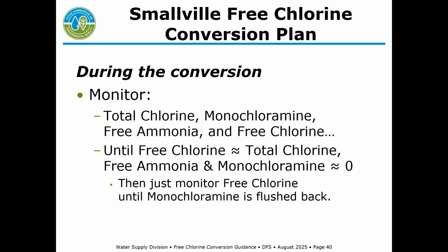And I'm just reiterating, I know I've said this before, but you're going to monitor total chlorine, monochloramine, free ammonia, and free chlorine until the free chlorine is about equal to total chlorine, and free ammonia and monochloramine are about 0. And then you can just start monitoring free chlorine until you get the monochloramine flushed back.